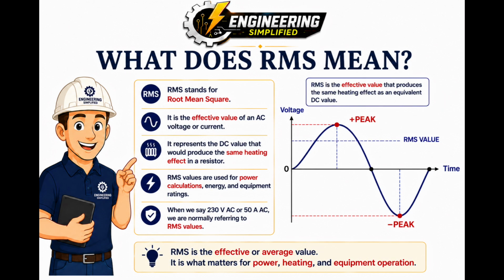Now let's look at RMS. RMS stands for root mean square. RMS gives us the effective value of an alternating voltage or current. A useful way of understanding this is through heating. An RMS current flowing through a resistor produces the same average heating effect as an equivalent DC current. So, for example, an AC current of 10 amps RMS produces the same average heating effect in a resistor as 10 amps DC. This is one of the reasons RMS values are so useful in electrical engineering.